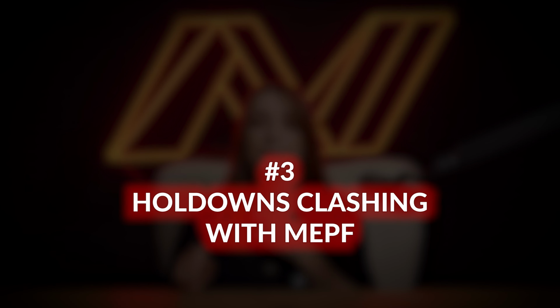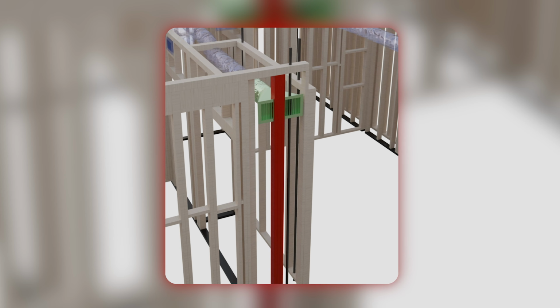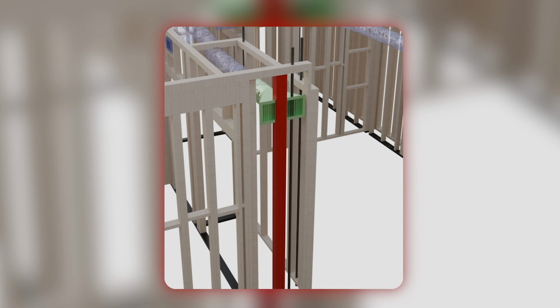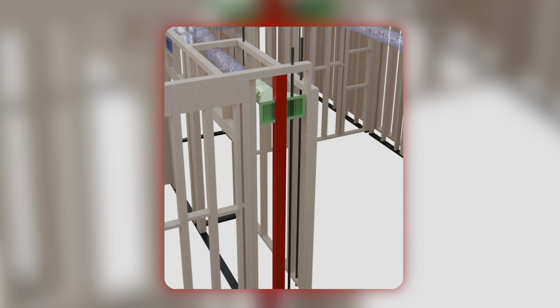Holdowns clashing with MEPF. Holdowns are critical for structural stability, but when they're placed without coordination with MEPF systems, it creates major problems. It happens more often than you think. Structural rods land exactly where a duct needs to run. Holddown hardware blocks the space needed for plumbing stacks or large electrical conduit, and no one realizes it until the mechanical, plumbing, or electrical crews are already on site.